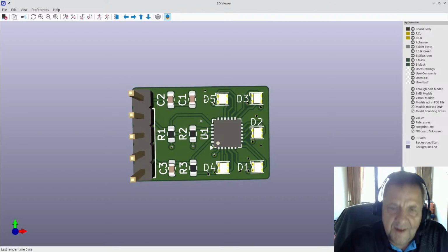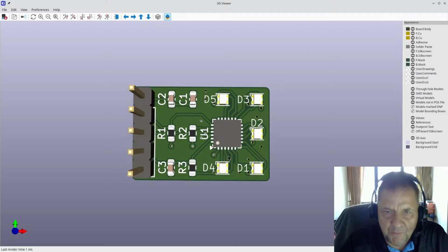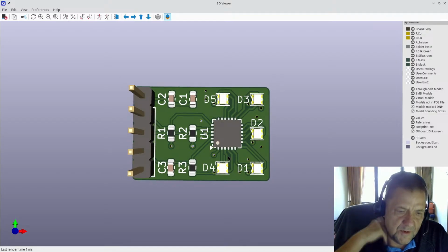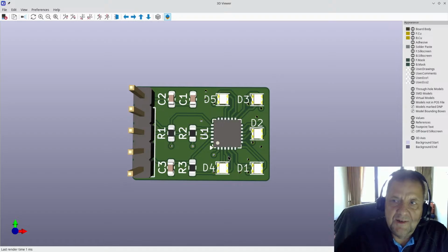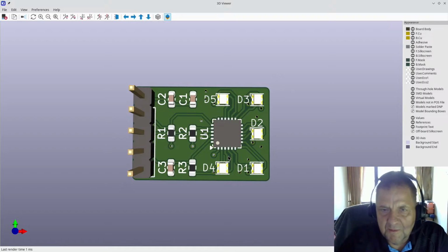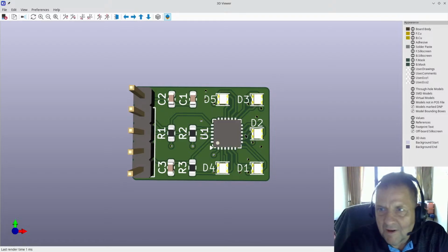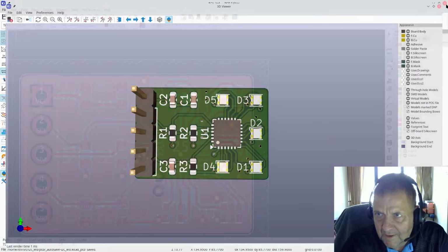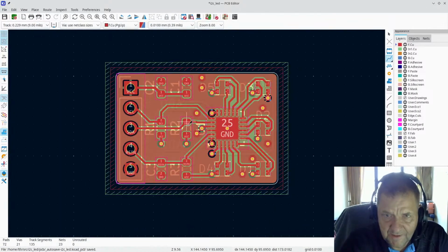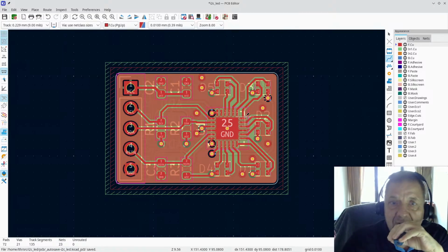I mean, these days, as I mentioned in the first video, this is a somewhat pointless board, because these days you would use the intelligent NeoPixel board instead, which you can drive with a 1 wire along a string of them. You don't need this GPIO expander to run one of those, so it's easier, especially if you've got a lot of LEDs. And they are almost as cheap as this one, if not cheaper.